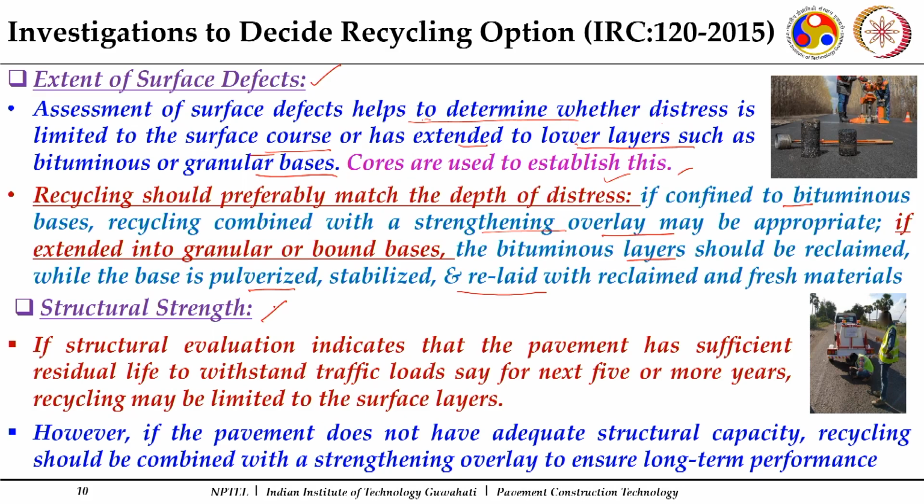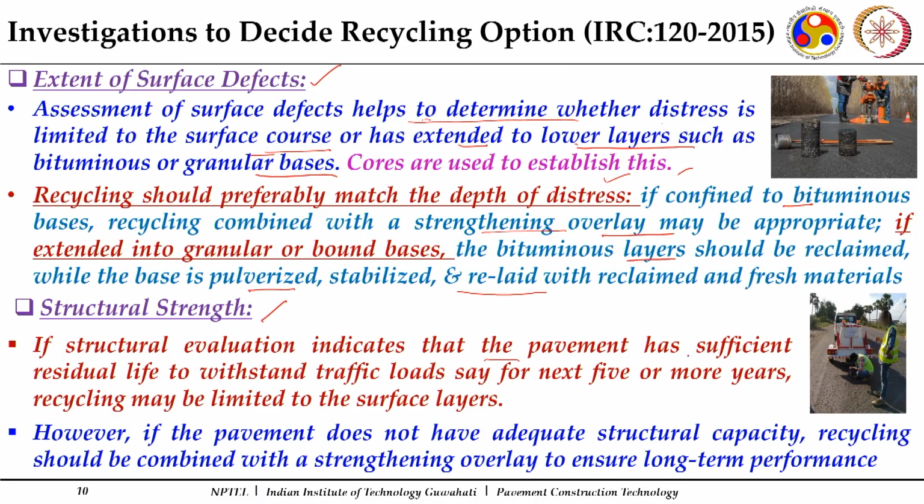Structural strength, as I mentioned, is another important aspect which we need to work out: how much is the current strength, and for how many more years the existing pavement can serve. If it can serve for a good number of years, say 4 or 5 years or more, then we can work it out by just providing an overlay also. So if a structural evaluation indicates that the pavement has sufficient residual life to withstand traffic loads for the next 5 or more years, recycling may be limited to the surface layers only. Only the top layer which has shown some distress can be a candidate for recycling.